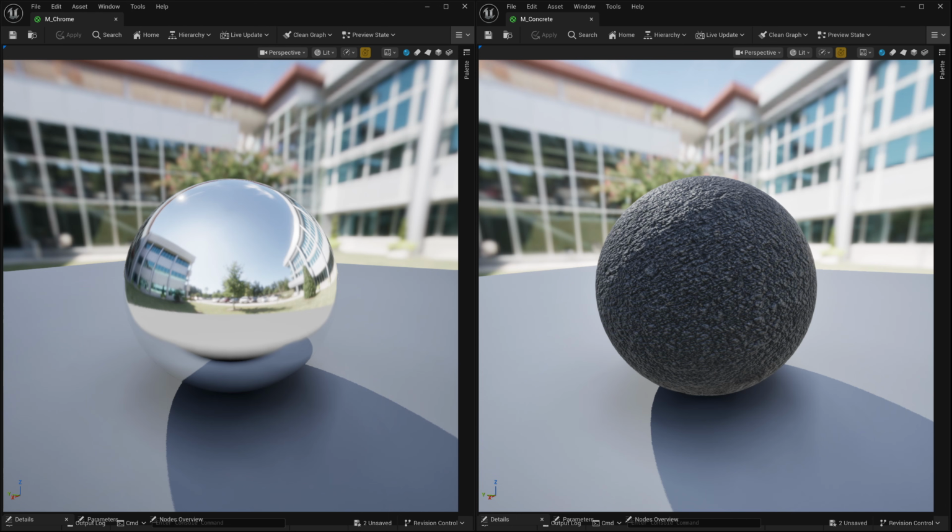In this case that we're looking at right here, when the surface is a metal in the PBR workflow, it reflects a lot more specular reflection at the facing angle, generally about 60 to 100%. But most metals are probably in the 90% range. And non-metals generally reflect about 4 to 7% as specular reflection at the facing angle. And pretty much almost all materials reflect 100% or close to it at the grazing angle, at the completely side-facing angle.